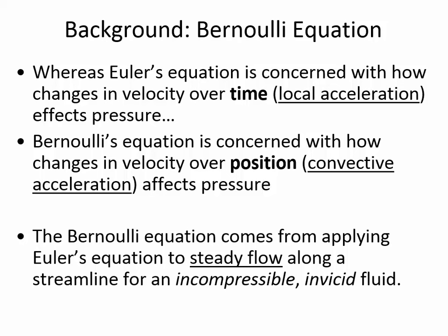But now look at the next assumption, inviscid. Now you may not know what that term means, but you know what it goes along with. It means viscosity. So an inviscid fluid is a fluid that has no viscosity. Well, that fluid doesn't exist. There's no fluid that has no viscosity. All fluids have some. Liquids have a pretty high viscosity compared to gases. Gases have a very low viscosity. So gases are good at satisfying the inviscid assumption. They were bad at satisfying incompressible, but gases are good at satisfying inviscid.